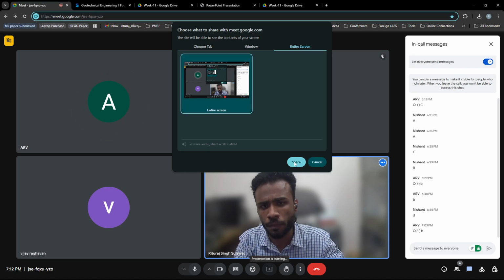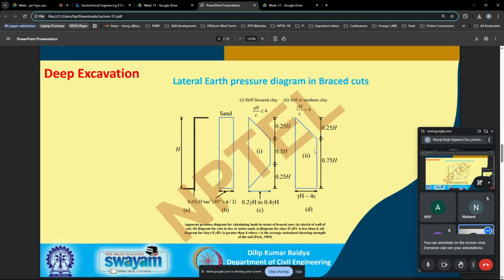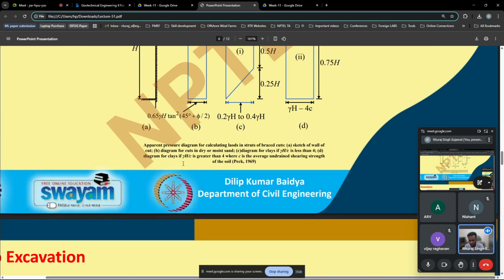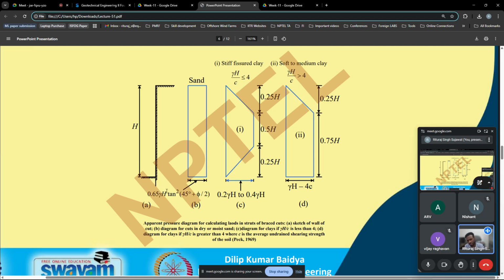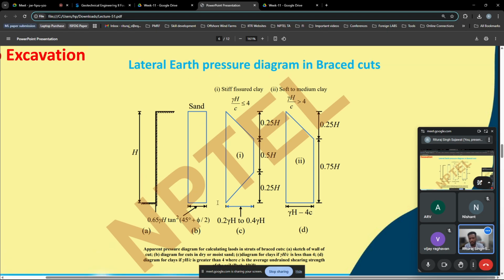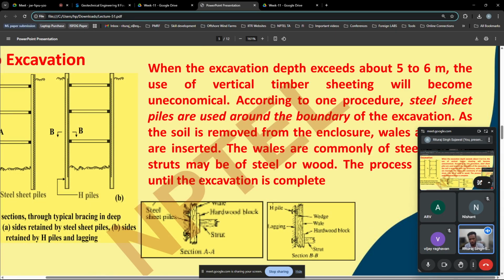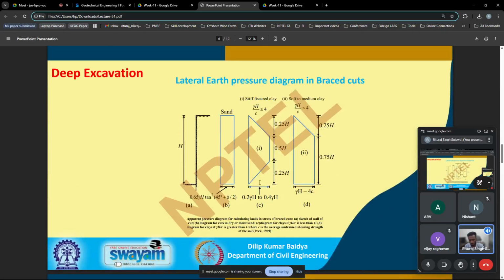No, sir. These are the three cases. So for the sandy soil, this might be the empirical relation which they have considered. So there is no such mechanics basically involved which we can take into account. So they are not considering the entire strength; they are just considering 0.65 times of that particular strength, right? Yes. But the reason should be given.